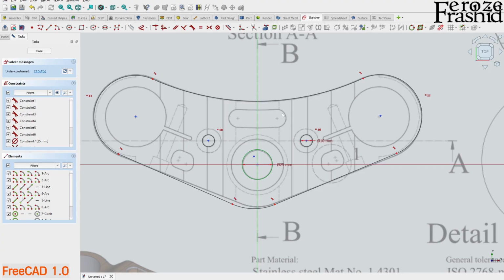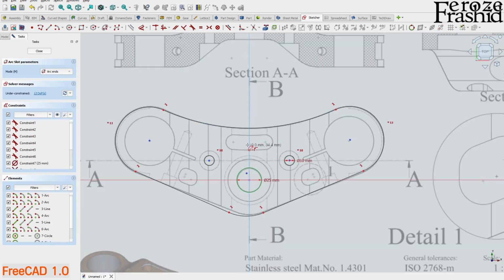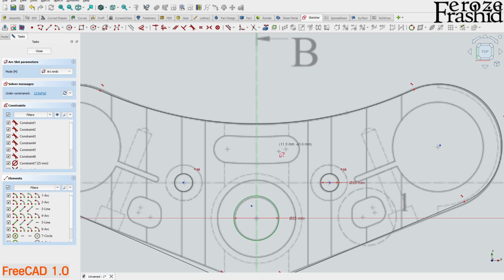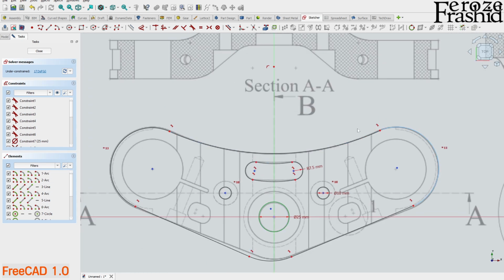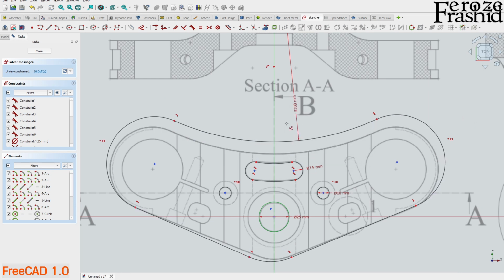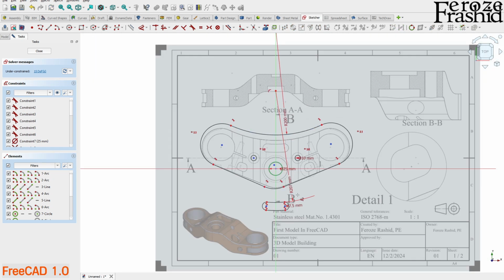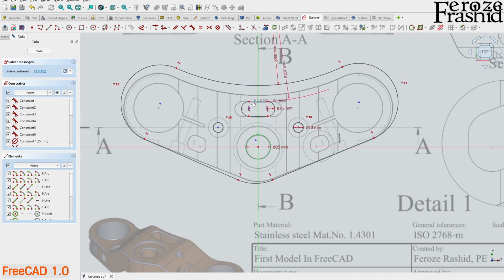Let's draw this arc slot, which is a curved slot. So take that arc slot. To draw an arc slot, it's a big arc, like the radius is big. So let's take the center first and hit the first center of the arc, the second center, and now it's asking you to apply the radius, which is 7.5 millimeter radius on the end. Right. Okay, I think this arc is radius 200 millimeter, and then this one is 207. Looks way weird. Let's bring it down there.